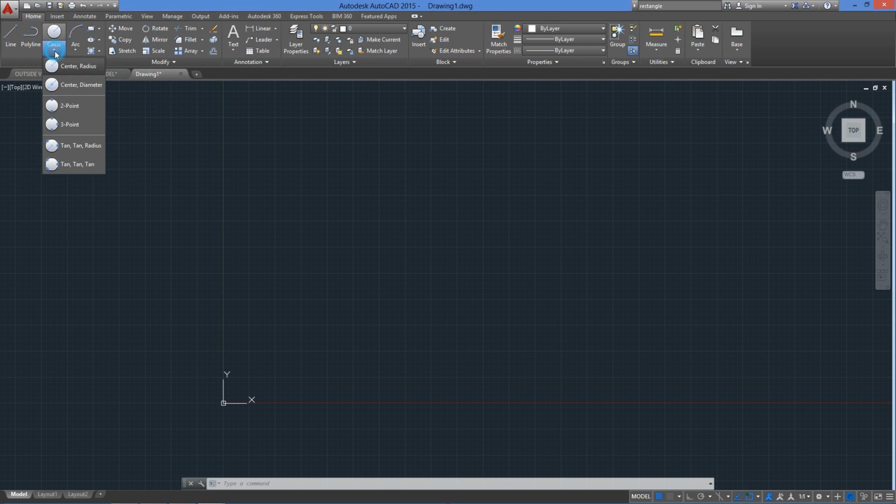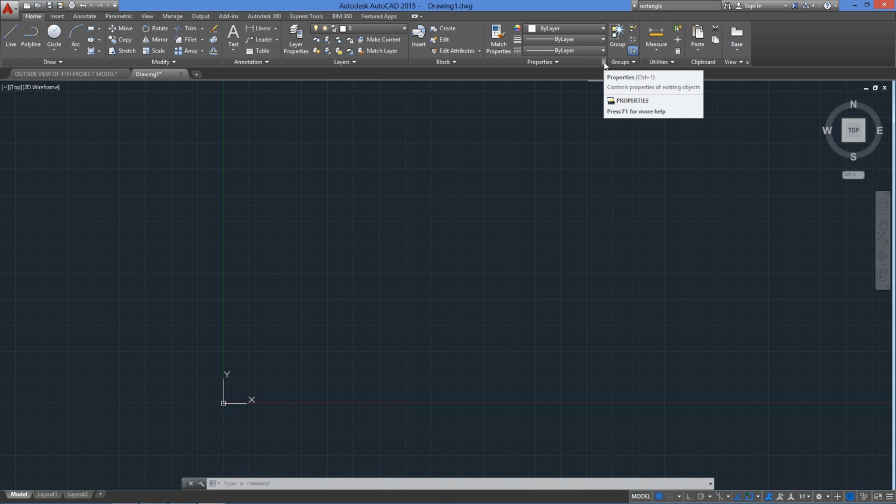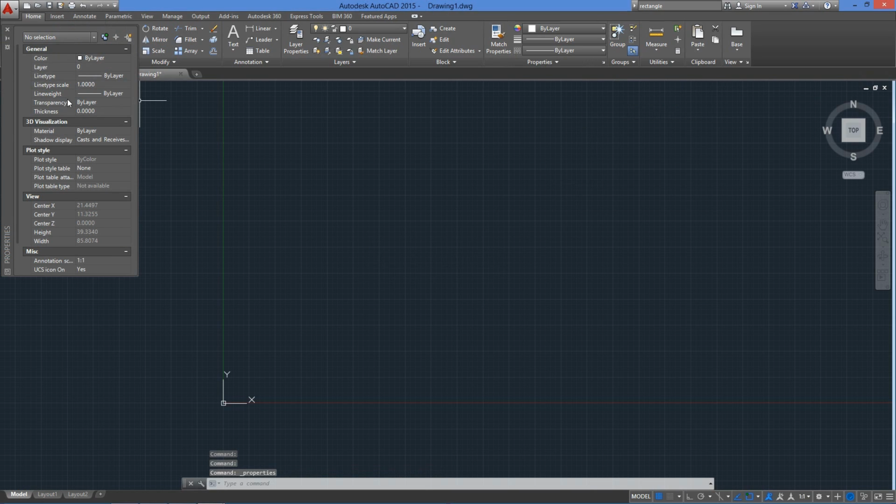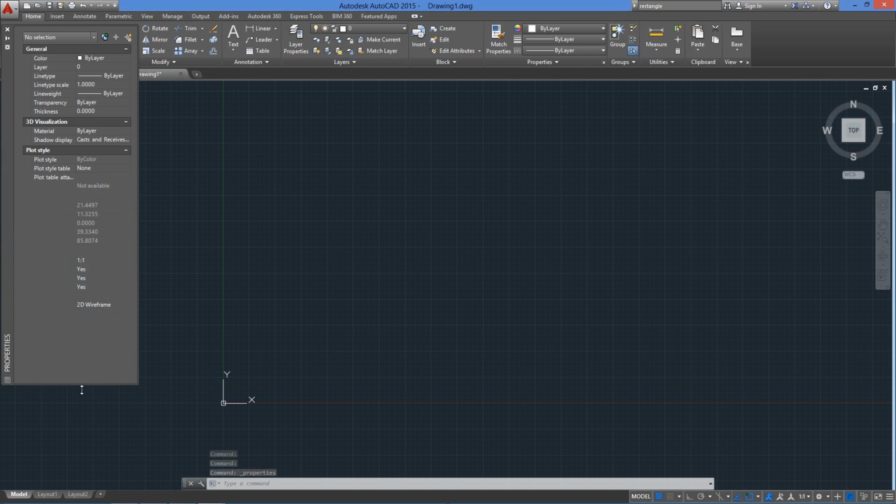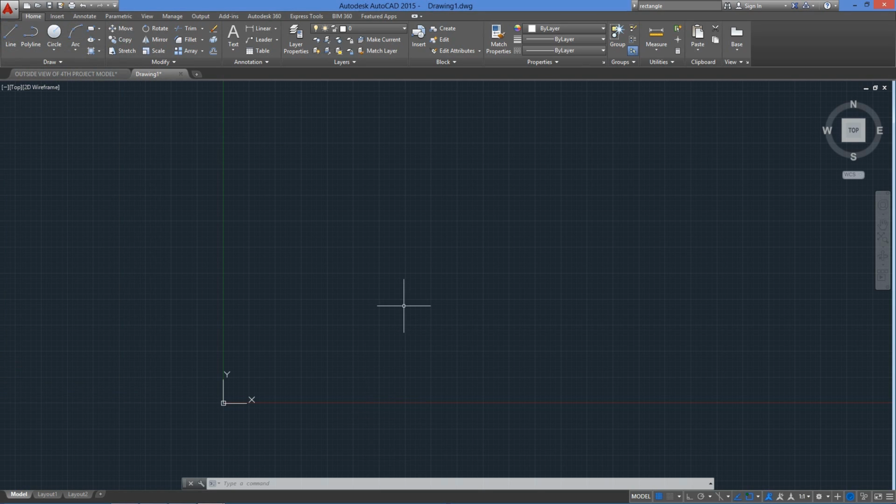For example, we click the one for command circle, and we see it has multiple options to create a circle, and the same applies when the triangle is at the bottom of the module. If we pull the options, we see it has other commands available. Now, we might see instead of a triangle, an inclined arrow on the right, as is the case here in the Properties module. This indicates that we have available a tool palette, which will include a set of extra options for commands, settings, or tools, depending on the specific palette you select.